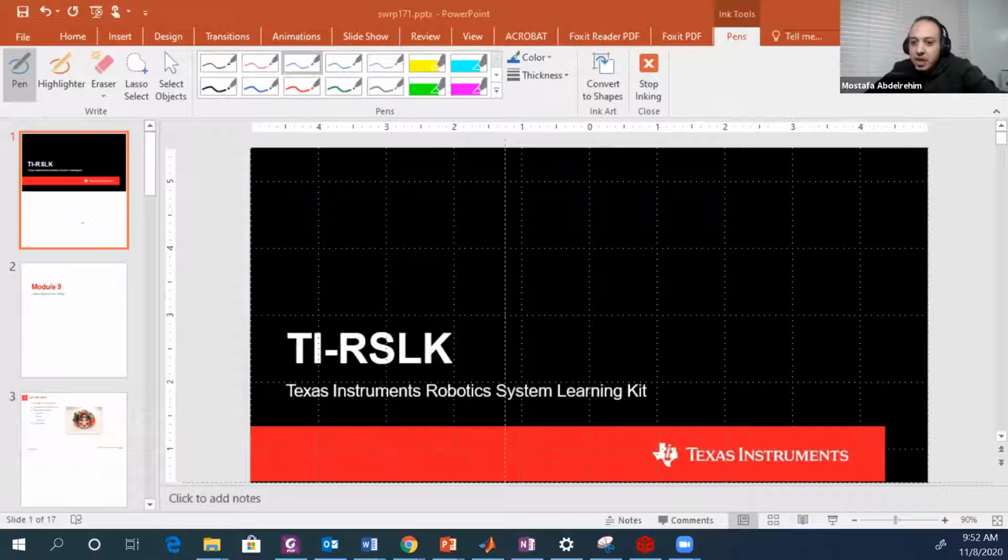So we're gonna talk today about the timers, and we're gonna start with the simplest timer in our microcontroller, our robot kit microcontroller, which is called the Systick Timer or System Timer. It's a very simple one. We're gonna use it in two simple applications: how to measure a delay and create a delay, and finally to control the speed of the motor, as we're gonna see tomorrow on Monday. Okay, so let's talk about this guy.